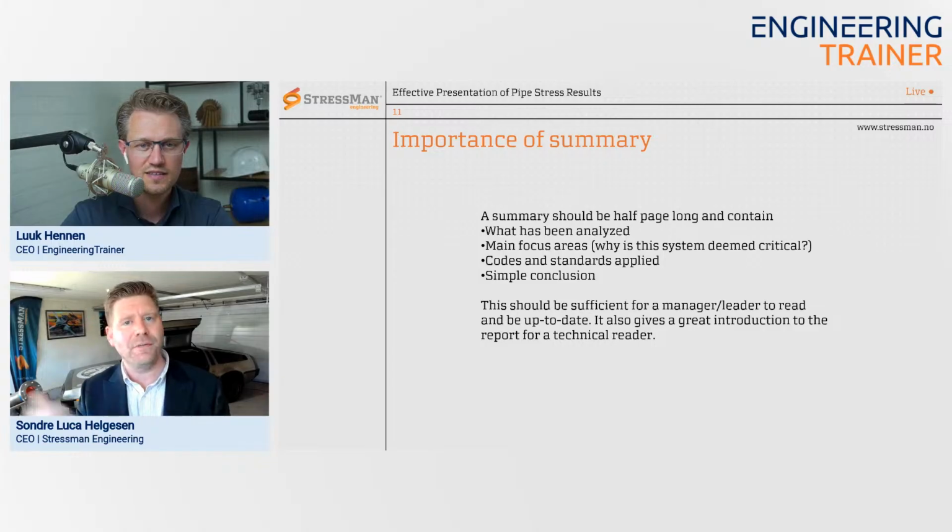If we do an FEA of a nozzle, using Nozzle Pro or ANSYS or something, and we say it's okay, but the vendor of the equipment didn't confirm it, what's the responsibility afterwards, for example? That's one thing. Very often we do it just for internal sake, and we see that this nozzle has a lot of capacity. Let's ask the equipment supplier to do a recheck with our loads, for example.